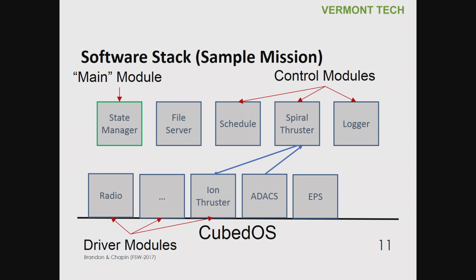And in a small spacecraft like a 6U CubeSat, which is one we've been looking at, you just don't have room for auxiliary thrusters that you would have in a larger spacecraft to take care of that functionality. So it makes it possible to have a deep space 6U CubeSat that can handle all of its momentum dumping capabilities. And so that's a significant piece of software that will be part of this. It's a fairly complicated algorithm, and one of our grad students is working on that for his master's thesis.